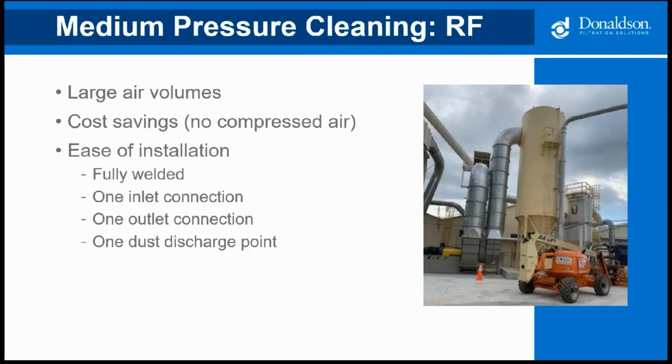The RF collector is a workhorse in the woodworking industry. It can handle large air volumes and large volumes of dust. It has a cyclonic inlet that provides some pre-separation prior to reaching the filters. The bags are cleaned with a medium pressure produced by a positive displacement blower, thus saving you on expensive compressed air. The RF also has a single inlet, single outlet, and single dust discharge point.